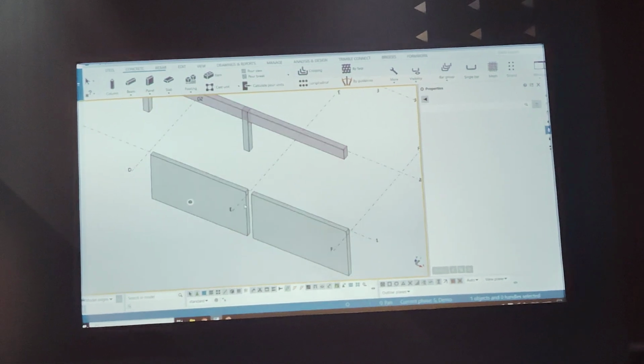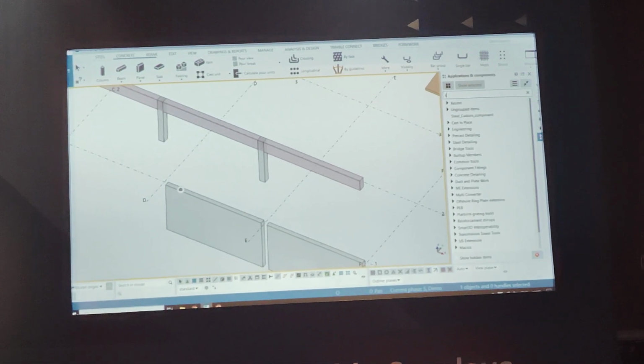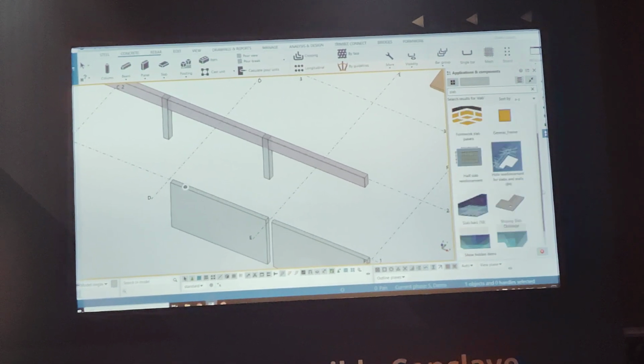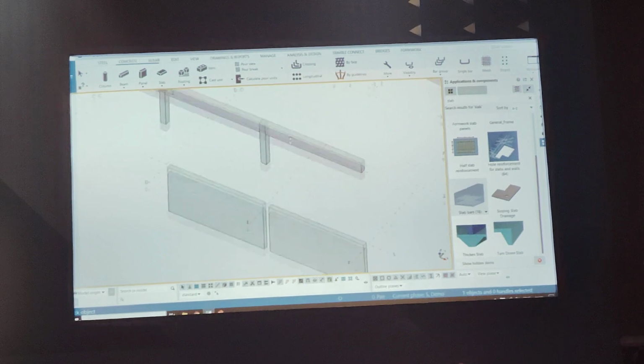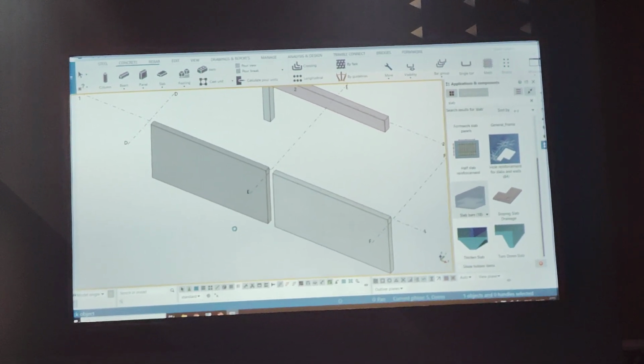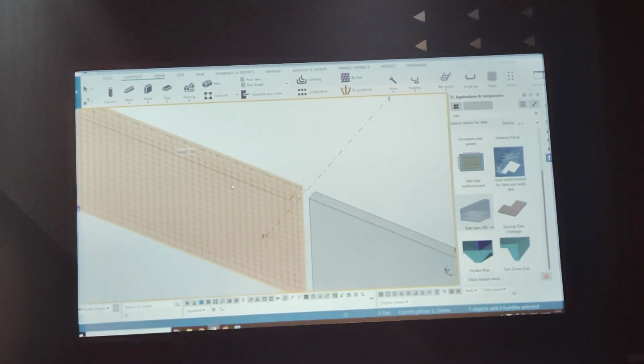So to apply reinforcement, like I said, we have some tools in here for slabs or wall panels. I can use this slab reinforcement tool. You can say slab bars. I can click. It creates the reinforcement for me. Okay, this is a simple example.